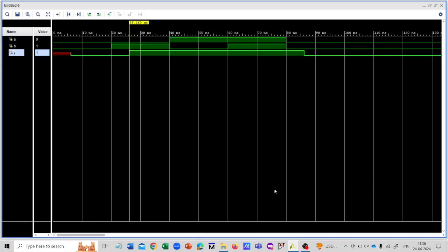And this is the root cause of the limitations in operational speed of various circuits. We are all accustomed to hearing about how fast a mobile phone or how fast a computer operates in terms of the clock frequencies. The root cause of all these limitations is the propagation delay, as we have seen now. And the other effect of delays are the glitches, which we will take up in the next video.